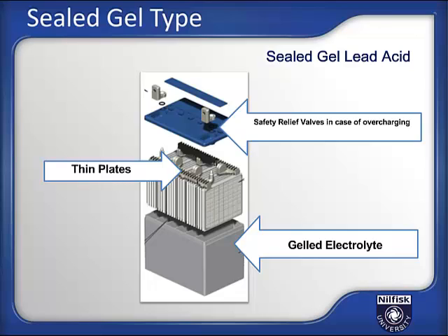So compared to flooded batteries, gel batteries are more sensitive to high temperature environments and more vulnerable to things like thermal runaway during abusive charging conditions. One of the major issues in gel batteries is they cannot be fast charged on a conventional charger. If they are, permanent damage results. So basically what happens if the battery is overcharged is that voids develop in the gel. These voids never heal because the electrolyte is immobilized. So once you create a void in the electrolyte, you have in effect reduced the battery capacity.